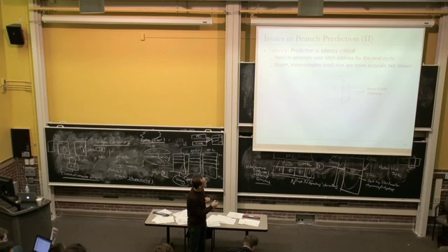So we want to generate the next fetch address. It could be the BTB target. It could be the return address stack target. It could be the indirect branch predictor target. It could be the resolved target from the backend. So now you have a big mux, and this logic could be on your critical path.